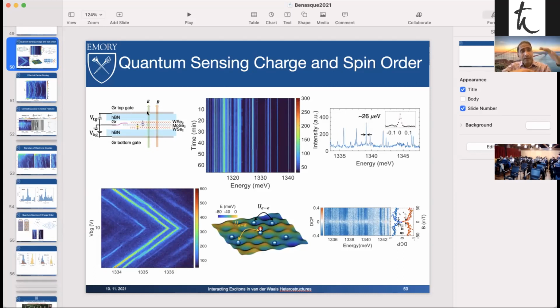This graphene gate is going to screen out any charge fluctuations you might have and give you sharp, stable lines. We have also played with the thickness of hBN. It seems like we don't need super thick. In this case it was 300 nanometers, but perhaps thinner will be fine as well. But I think these large graphene gates are helping to reduce the charge fluctuation. That's my guess. Or perhaps it's a combination of sample preparation and that. Does that answer your question?